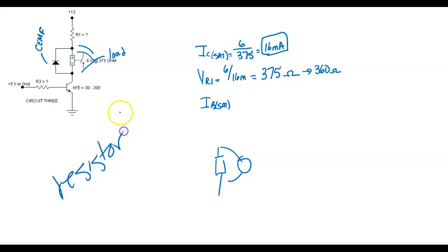A resistor. So I put another resistor in series with it to drop the rest of the voltage. We were working over, we had a 26 volt coil, and the only thing we had over in the motor control lab was 120 volts. How can I run a 26 volt coil on 120 volts? I couldn't. But what did I do? I put a resistor in series with it. Worked fine, right?